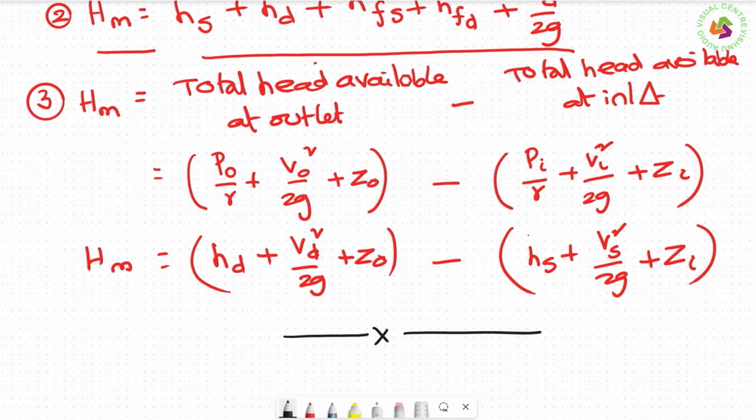What we define, just concluded: number one is suction head, that means from the center of the pump to the water level in the sump. Then what is delivery head? From the center line of the pump to the delivery point, the water level in the delivery tank. It is all heights that we measure, not just lengths, it is vertical heights. Summation of suction head plus delivery head is the static head. Then we have the manometric head.